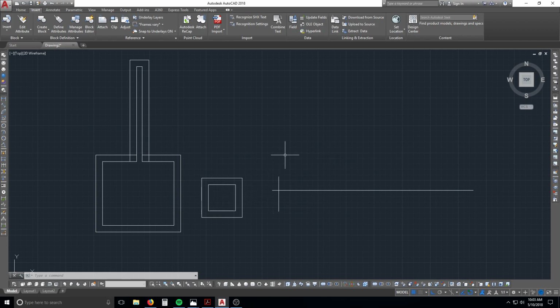That's a powerful one. If you're drawing something and you know it needs to be moved over slightly, or made bigger, or you want multiple copies in a row like a ladder or a series of lines, you can quickly copy or make an object slightly larger just by offsetting it.